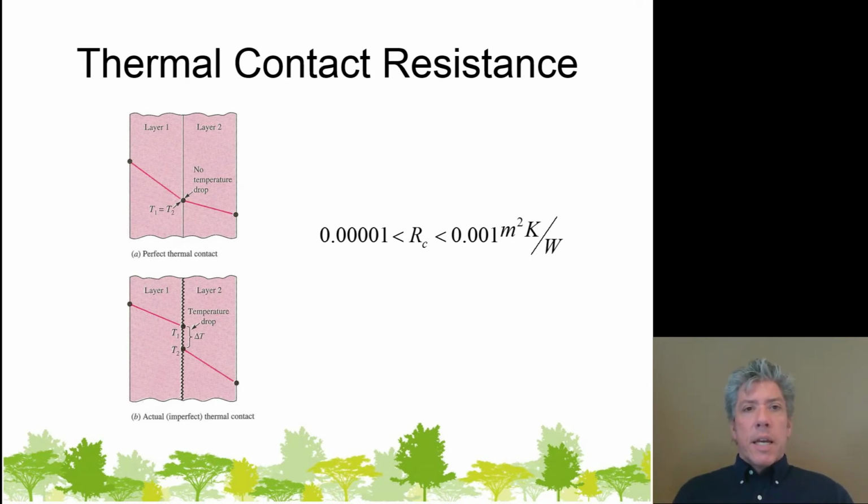Well, it turned out that when I took this thing apart and I took the chip out, I had to take a heat sink off the back. And you could actually turn it over and look at the array of mirrors and see a pattern where you could tell the mirrors were not working properly. And if you turn over to the back, the heat sink compound they had used peeled off and separated very easily from the chip in the very area where the mirrors had failed. It matched exactly, so the messed up pattern on the screen matched exactly the failed heat sink compound on the back of that chip, and that's why it failed.